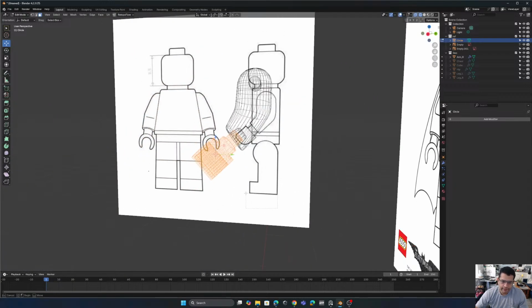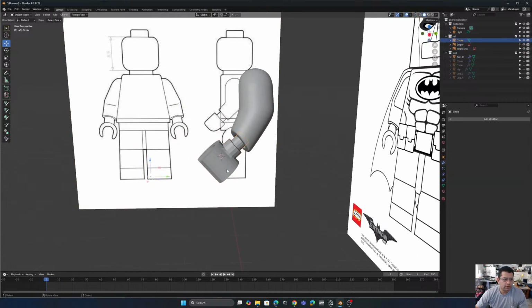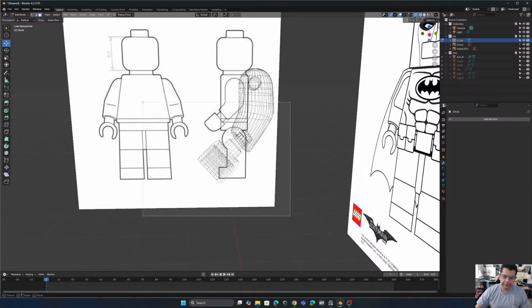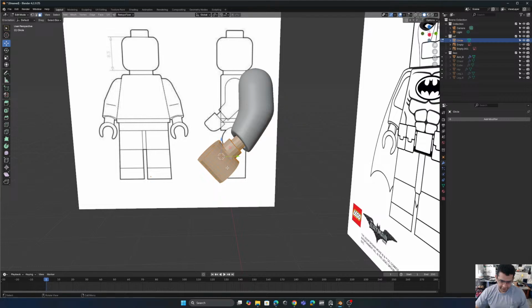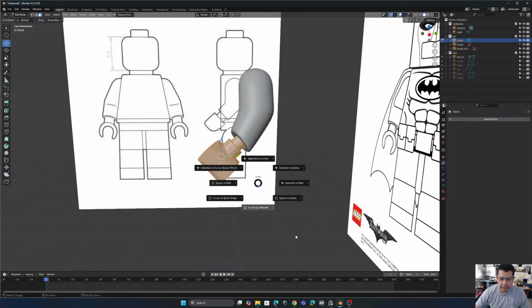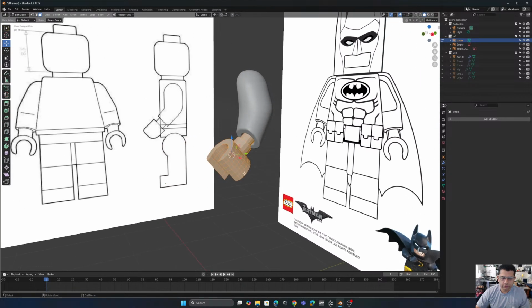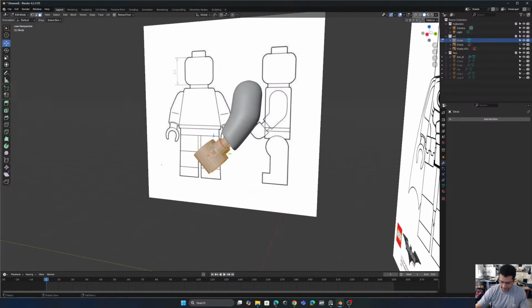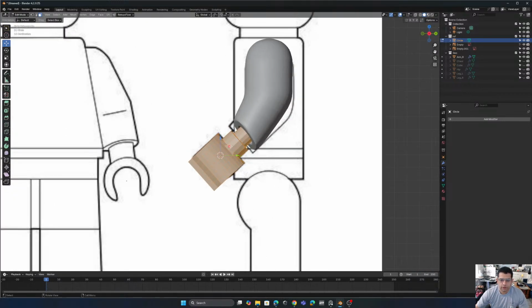Again, you are outside the edit mode. In object mode, you press tab, Shift Z to go to wireframe mode, select all the faces, Shift Z to go to shade mode, then right click, Shift S to get this menu, and we go to cursor to selected, and the cursor is gonna move to the center of the shape. Now we have so much more control in the movements. There you go.